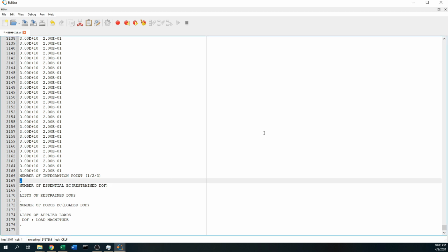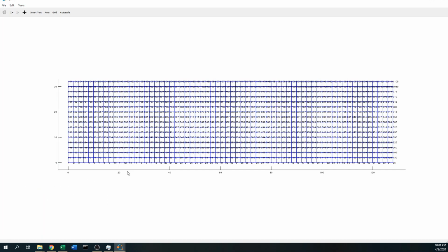We need two integration points. Number of essential boundary conditions, we have not seen the picture yet. Well, we're gonna put 7 like in the morning. Essential boundary conditions for the support. I'm gonna distribute the small width finite length of the support, so we will not bump up into the issue I mentioned already. What is that? The singularity. The list of restrained degrees of freedom, we cannot give it to you now because it is trying to open up the figure. Okay, there it is.